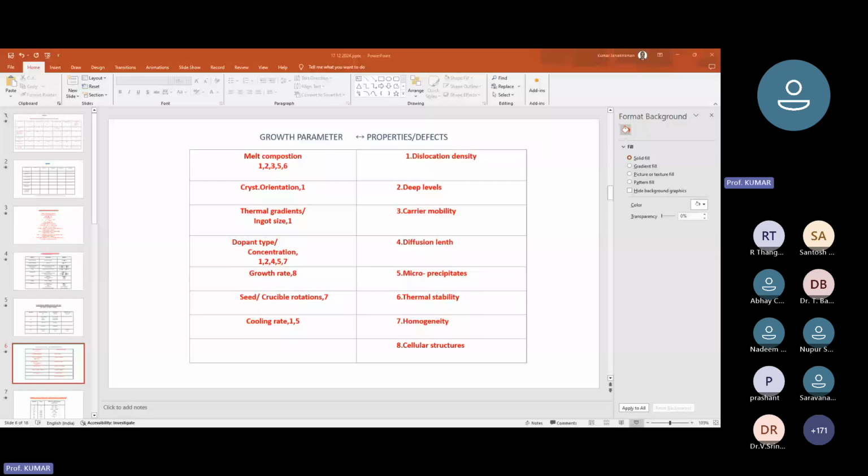So these are some of the common crucibles: platinum, iridium, molybdenum, tungsten, carbon, silica, alumina, all of which can be operated within these temperature ranges, and their melting points are also given here. But we also have to understand the type of environment in which you can use platinum or iridium. Generally, iridium is not used comfortably for RF heating, but otherwise you can use it for mostly resistance and RF heating, all these metallic materials in terms of a container and the type of heating. Whereas silica can only be used for resistive heating.